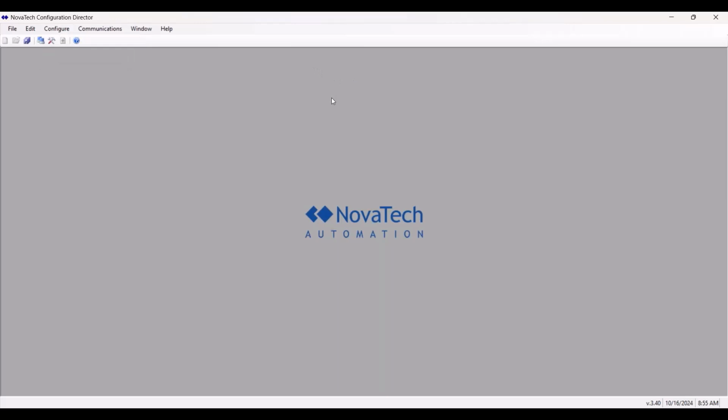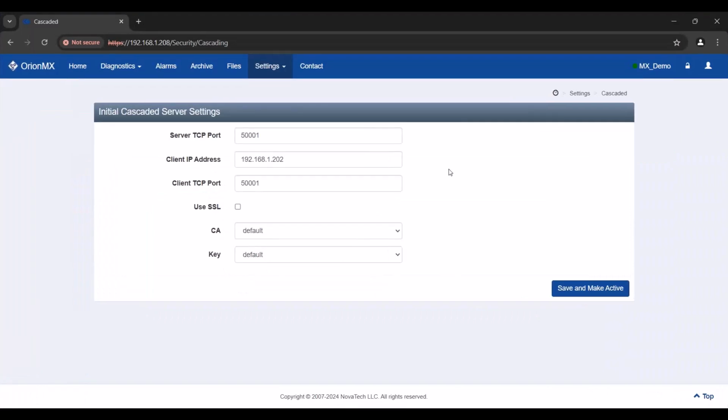One additional thing that I would like to show, because I think a lot of customers run into this. It doesn't really apply to the Alex Plus, because Alex Plus has separate cards for RS-232, for RS-485, and so on. But one thing I would like to remind people, if you are using a MX or an LXM, the serial ports on the MX and LXM are RS-232 or RS-485 software selectable.